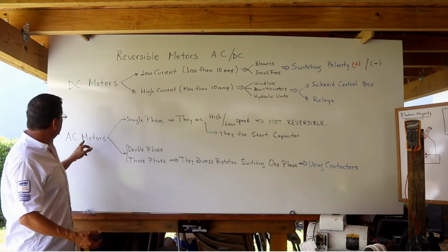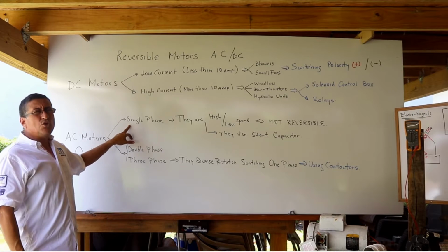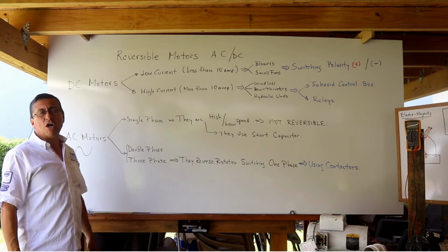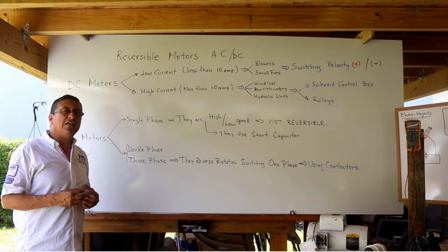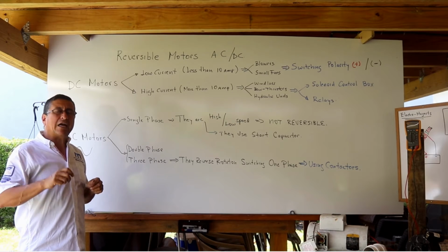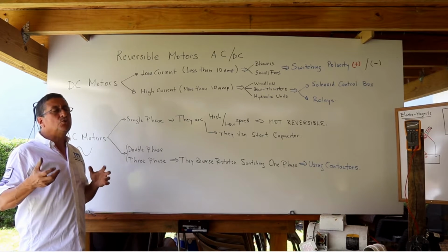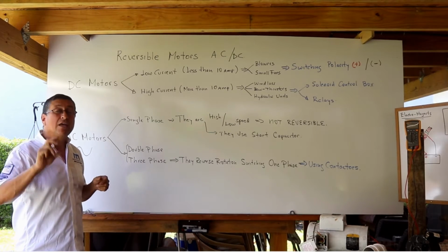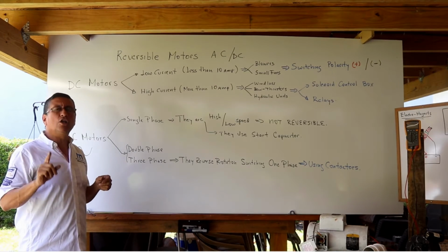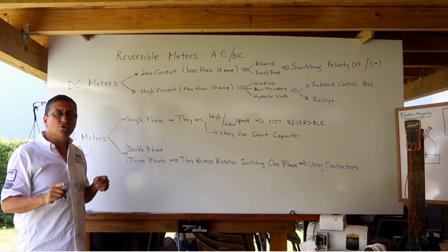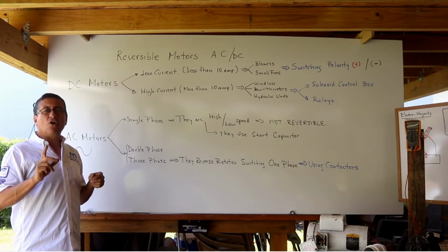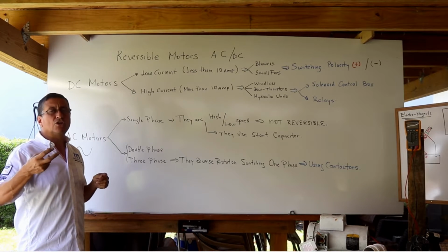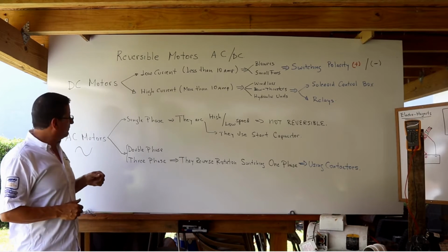In AC motors, can you switch the rotation in a single-phase motor? It's not common. If the motor originally is a split phase with a capacitor, you can switch the rotation of the motor if you switch the polarity on the capacitor, if the winding is a split phase. Not all single-phase AC motors are reversible. Only single-phase motors with a split phase and capacitor, you can switch the rotation.